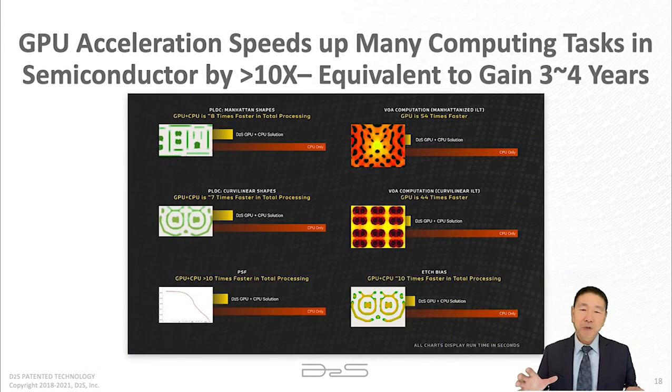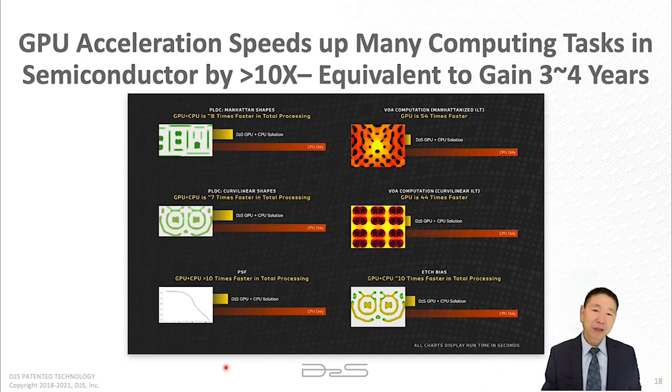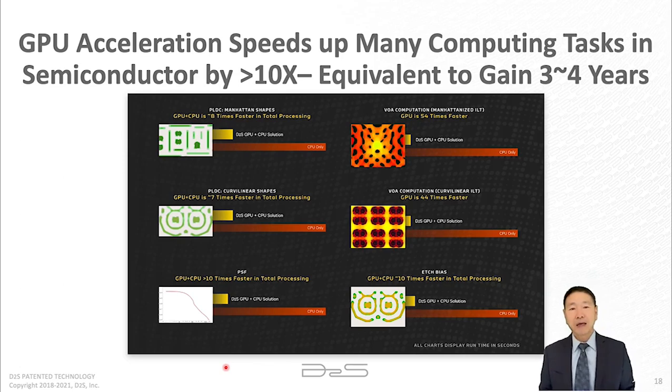First, let's talk about the GPU. Why do we want to use a GPU? Because GPU can accelerate those computations. The reason is that GPU is single instruction, multiple data, while CPU is single instruction, single data. So GPU has massive parallelization. Although CPU has multiple cores, we're talking about tens of cores, but on GPU, we're talking about thousands of cores. It turned out many calculations needed in computational lithography can be greatly accelerated by GPU. For example, Gaussian convolution, convolution with all kinds of kernels, and also the FFT. For those operations, GPU can accelerate it over 100 times. So GPU is good for ILT.